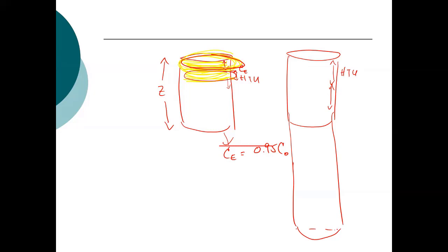Okay, so we're doing this with granular activated carbon right now. Can you do this with the powdered version too, or is that pretty much strictly added, like with coagulants usually? The reason you don't have a column with powdered activated carbon is because of back pressure. The porosity is too small, and it takes too much pressure to basically push the water through the column.